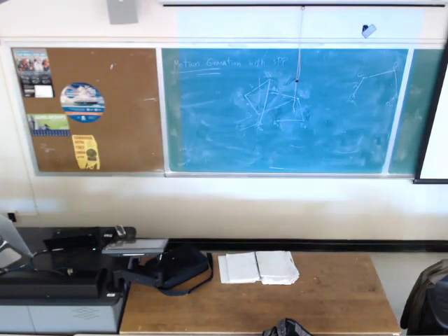So this is O2A1 and O2A3, the two extreme positions of link 2. Pick one point, C1. Draw a circle with this center and this radius. You are going to get C3. Connect C1 and C3 and extend.